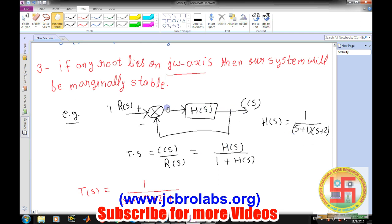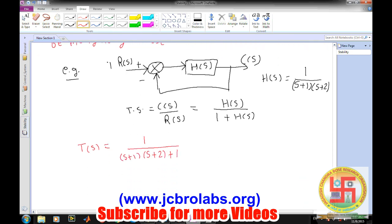But when we apply the feedback loop, the transfer function of the system changes. So we can't be sure whether our final transfer function will be a stable system or not. So let's figure it out. It will become S square plus 3S plus 3. If we try to find the roots of the system, this will not be so easy.